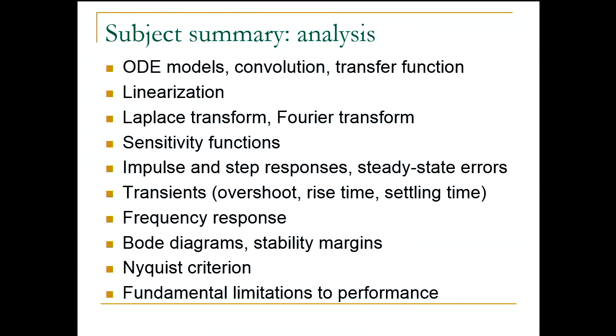So this difference in amplitude and phase tells you how the model of the system distorts the signal in steady state. So input signal is plugged in, and then it's distorted through amplitude and phase shift. So this then led to Bode diagrams where we were plotting how this amplitude and phase are related to the frequency of the driving input, right?